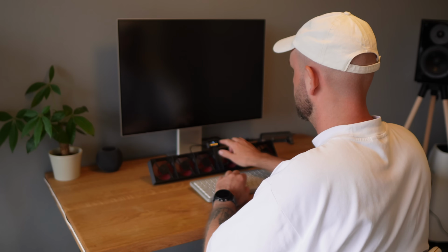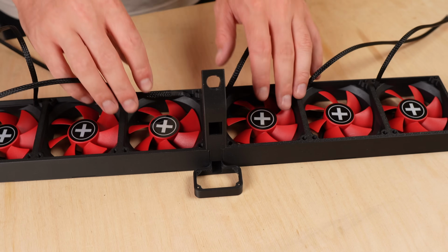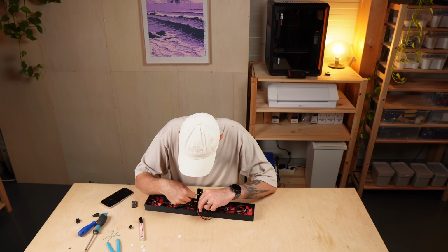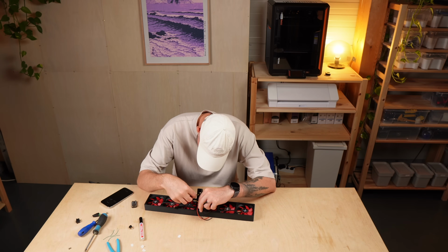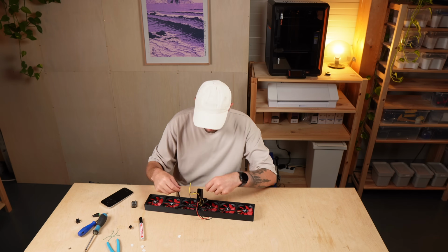One small note before you start. I designed the enclosure around the exact fans I used for this project. If that particular model isn't available in your region, make sure any alternative fans have the same external dimensions and mounting hole positions before ordering them. Otherwise, they may not fit the printed enclosure.